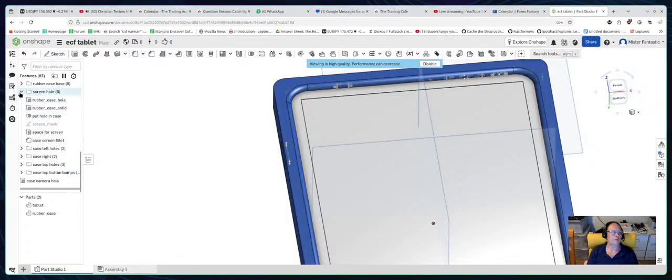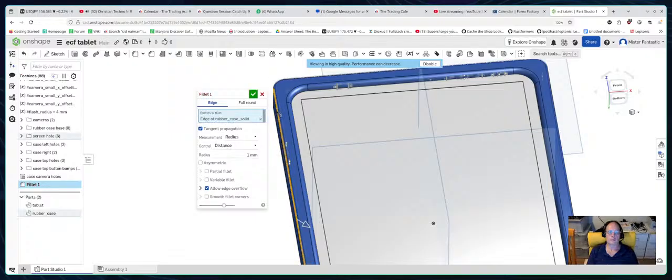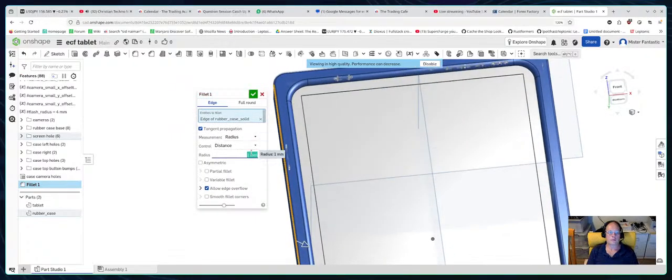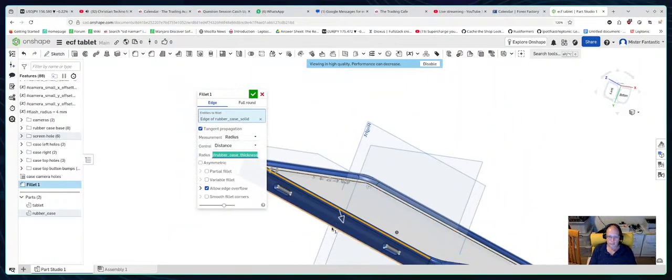So after the hole, should we put the? I remember, rename that to holes with the proper name. Let's just add a fillet for the whole case now. And it's going to be case thickness, 2.5mm. Maybe we should do the front and back the same.